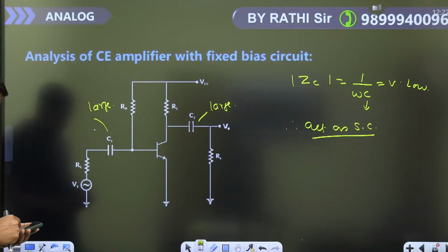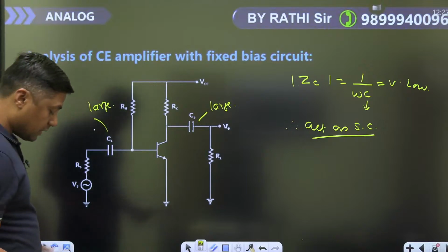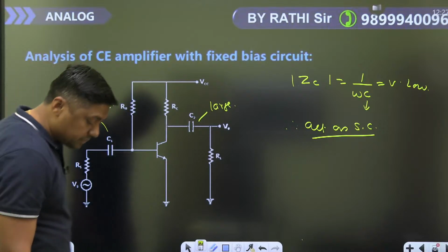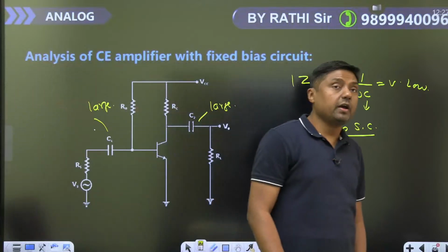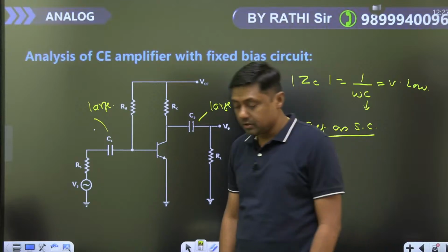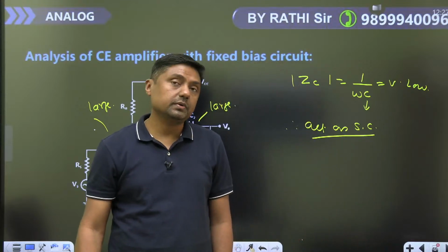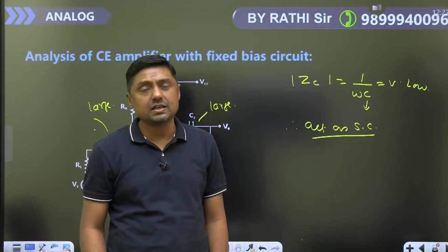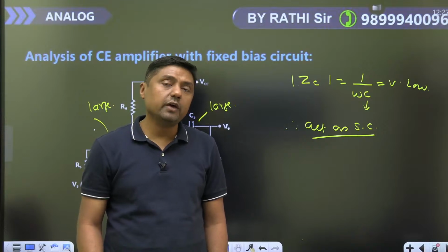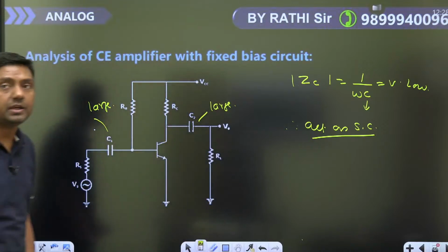हाँ, कनेक्शन को आप चेक करते हैं जरा. अब आप क्वेश्चन पूछ रहे हो, which one is the best, self bias circuit or fixed bias circuit. तो गाइज, in self bias circuit we have negative feedback, that's why that is stable, and in fixed bias circuit there is no feedback, that's why the point is not very stable. But if variation in the temperature is negligible or we want more gain, then we have to use the fixed bias circuit, क्योंकि वहां कोई negative feedback नहीं.